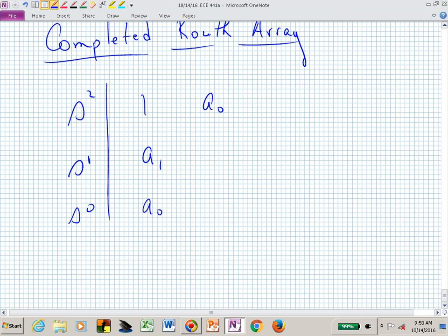So we've just shown that the Hurwitz test is necessary and sufficient for a second order. It's not for any other higher order. But using this test, we've now demonstrated that if you have a second order and you have coefficients that are present and positive, you can immediately conclude all of my roots are in the left half plane. And we'll pick up at that point with more examples on Monday.